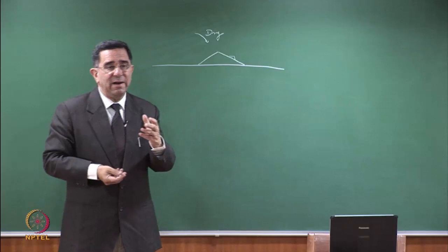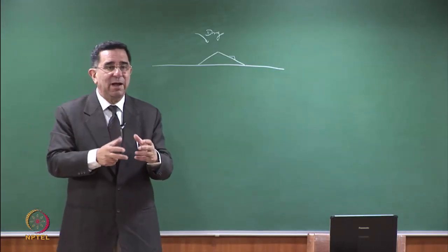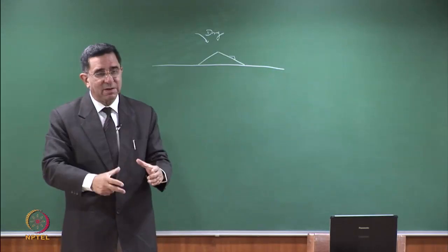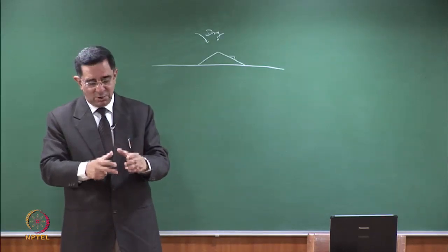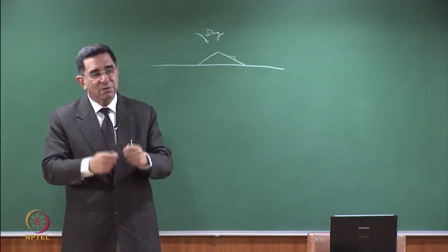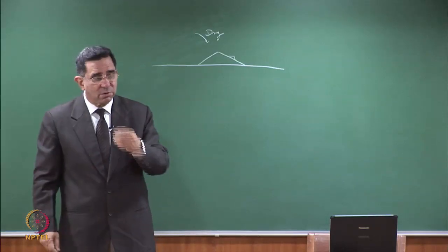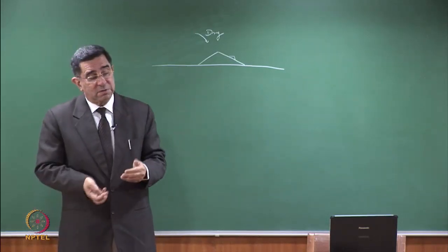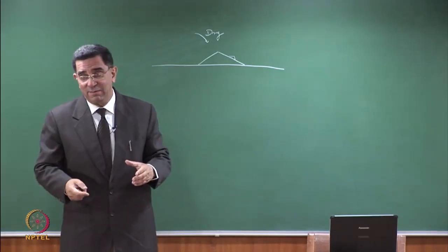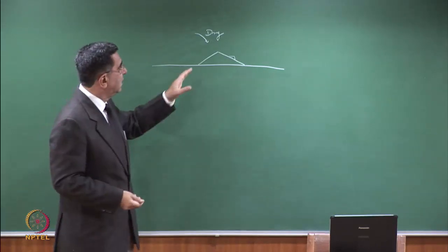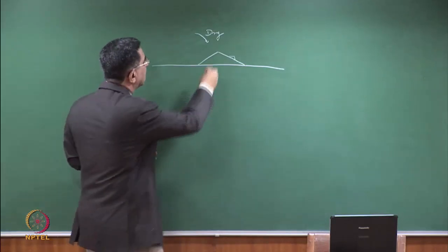It's like beach sand. You go and make castles of beach sand. Why? When the sand is dry, you can't make a vertical cylinder, but when the sand is slightly moist, you are able to make a vertical cylinder because there is negative pore water pressure on account of the liquid present. If you make the sand saturated, again you can't make it vertical. So when it is dry or moist, it will be like this.